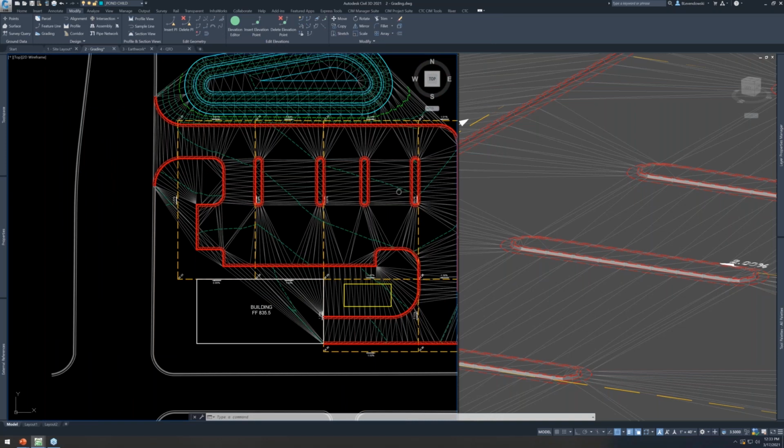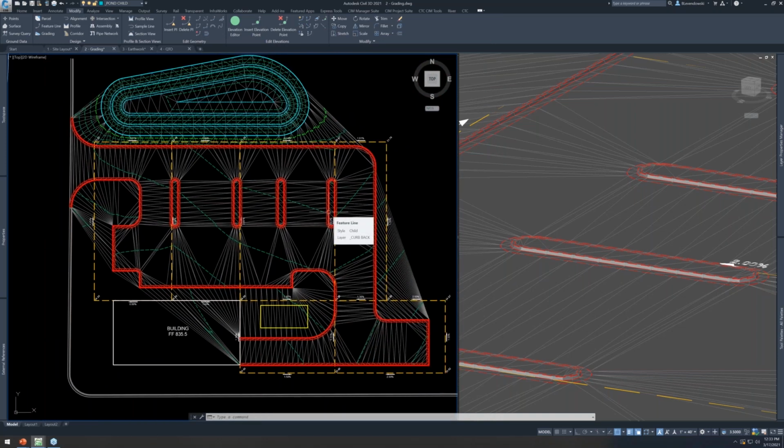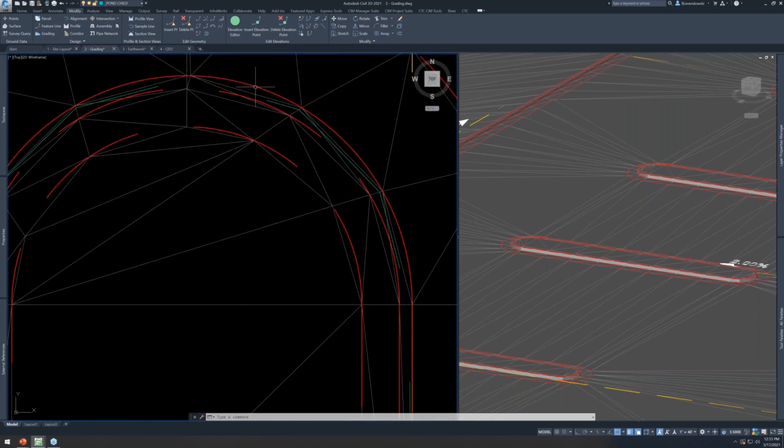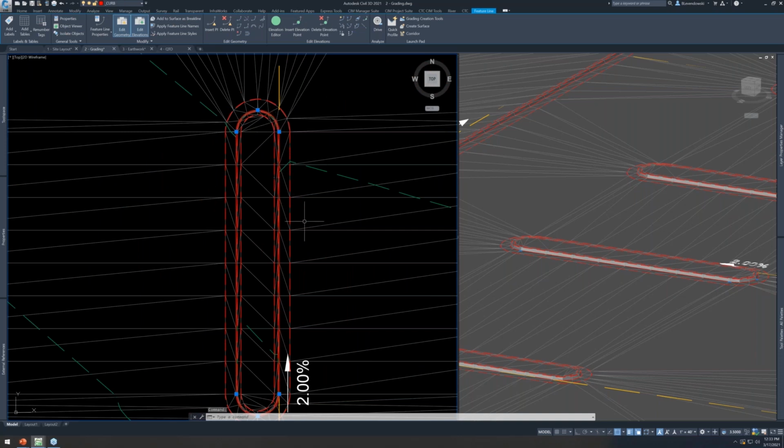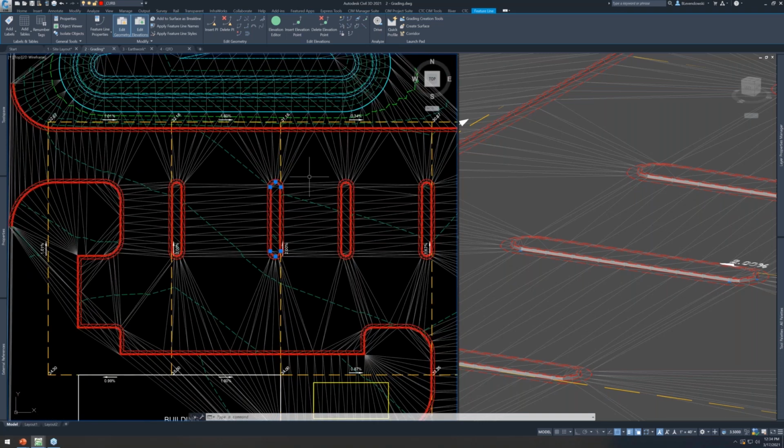Now, at any point, like I said, you can break free, so to speak, from the grid surface. At that point, you want to work with just your parent feature lines, just these gutter lines, adding certain little elevation points in here. Okay, something where you don't want to use the grid surface anymore. You want more detailed grading.